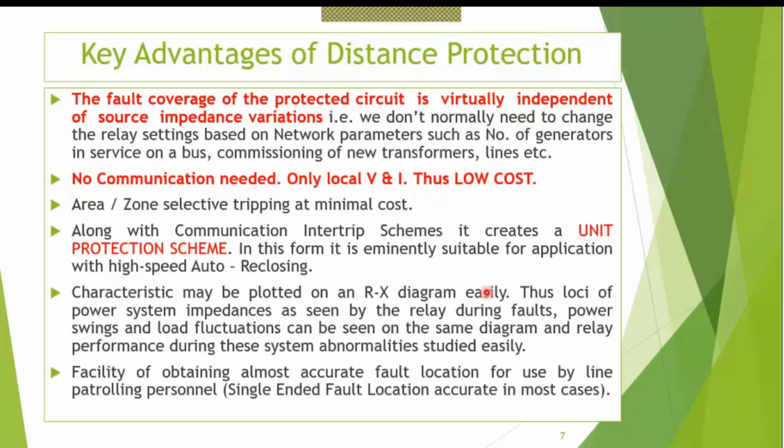In other forms of protection, it is a very individualistic protection, but in distance protection, the line protection, generator protection, and maybe transformer protection can be plotted in the same RX plane. So that is useful. If I am not able to explain this one, probably in the later slides you will get the idea what I am trying to say.